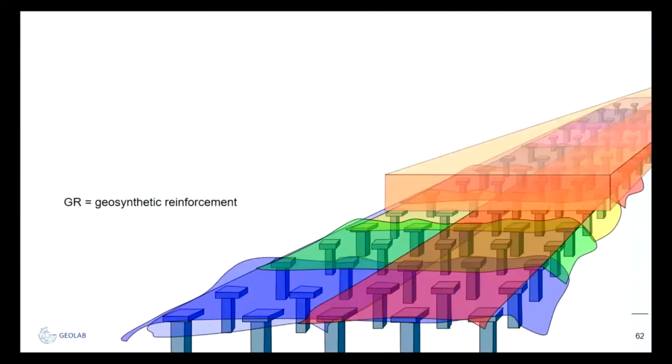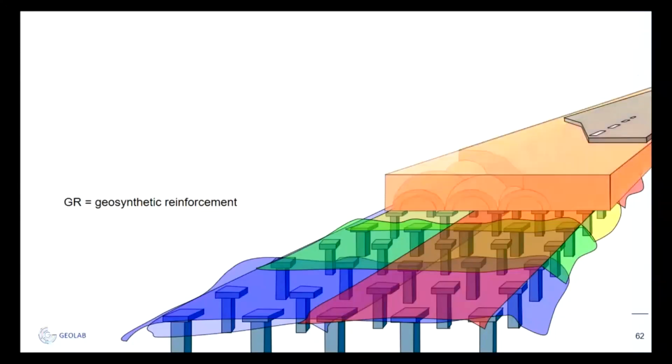And this embankment consists of sand or broken rock or a broken construction material, and sometimes in some tropical countries, tropical soil, that's right. And on top of this comes a road or a railway or any pavement. And within such an embankment, arching occurs, soil arching occurs. That means that the load tends to be transferred towards the stiffer elements, which are the piles.